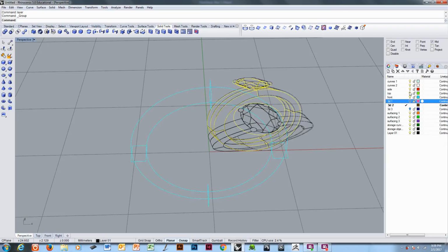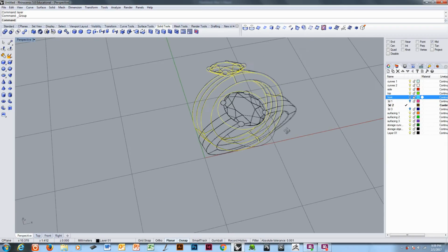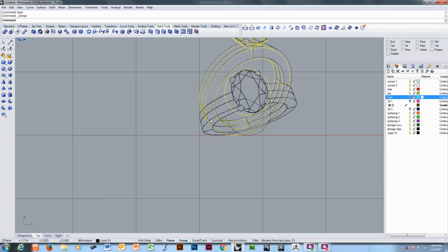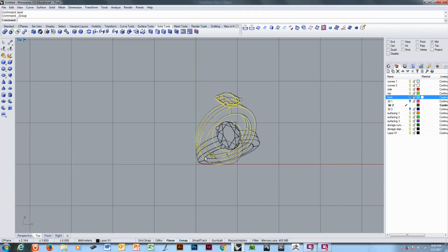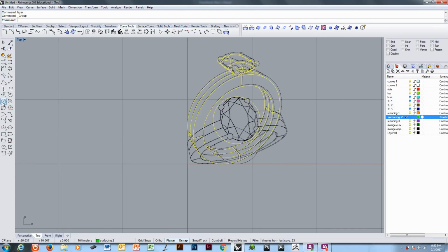I'm now going to turn off the maquette. And I'm going to go from 3/4 view to top view. When you're laying out drawings to be exported from Rhino in any way, shape, or form, you need to start working from an orthographic view. So we're going to do this in the top view. Here, Rhino can get accurate dimensions easily. I'm going to draw a circle, center radius, starting at 0, 10 millimeters diameter.